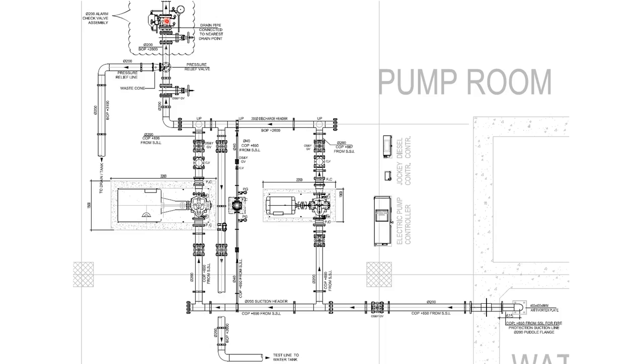Here, as I already informed you, the overpressure relief line is going back to the tank or it can be drained, and this overpressure relief line will be installed basically before the check valve of this diesel engine fire pump. Here it is shown in the discharge header line. However, please note, for electric fire pump in general we will not use this overpressure relief line.